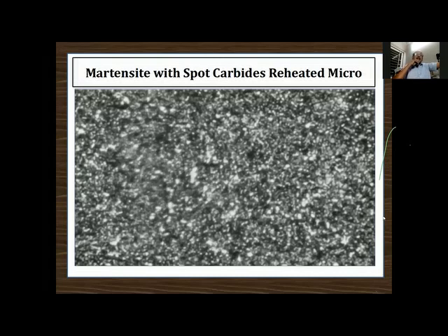There are two major types of carburizing cycles used. In one case, after carburizing is over, the components are cooled to a lower hardening temperature. They are held for a shorter time to homogenize the temperature, and then quenched. This is called the modified direct quench. This is commonly used because it saves a lot of energy, and it also gives fairly consistent results.